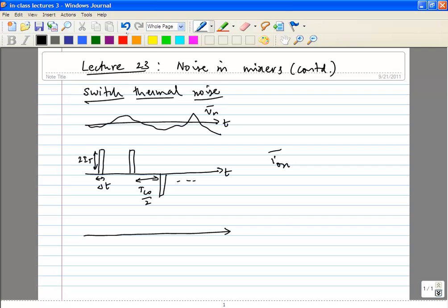to simplify the analysis, we'll replace it with another train of pulses, except that instead of having the pulse width change every period, we'll keep the pulse width constant, but change the pulse amplitude such that the overall noise added is the same.